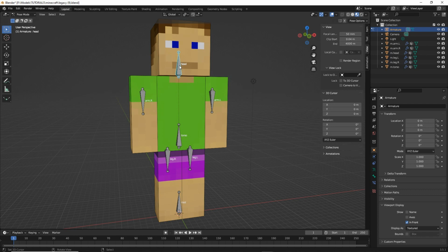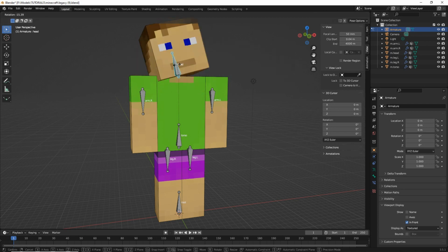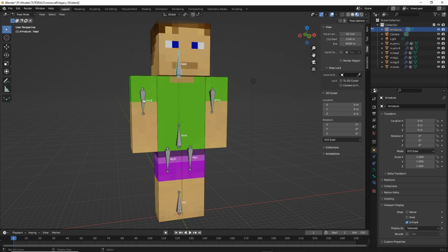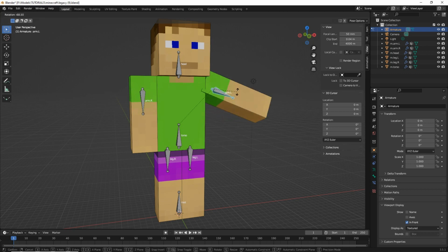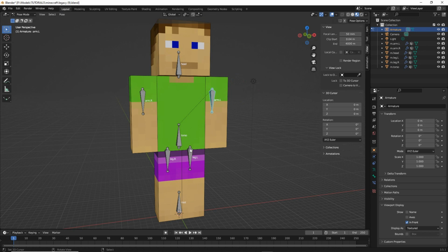If we select our bone and press the R key, we have rotation around the origin points for each of the specific bones. So we are positioning these when we're setting up the rig. As we discussed earlier, we are setting these up and positioning them relative to where the pivot should be for the element that's being manipulated.